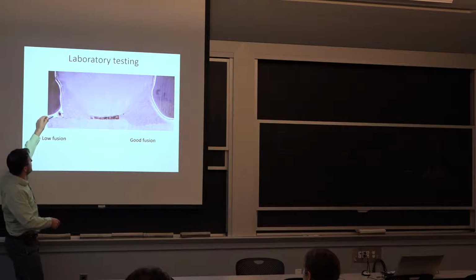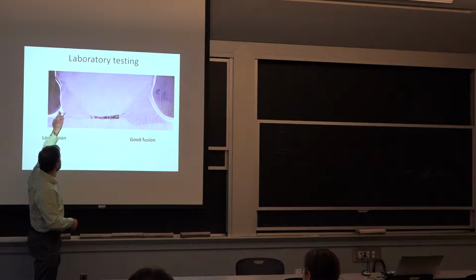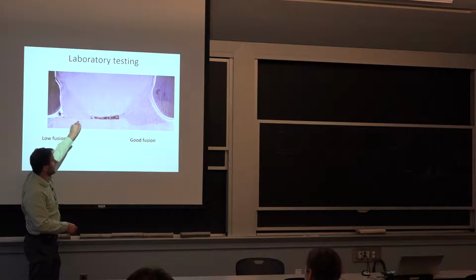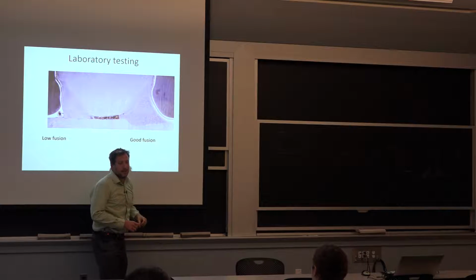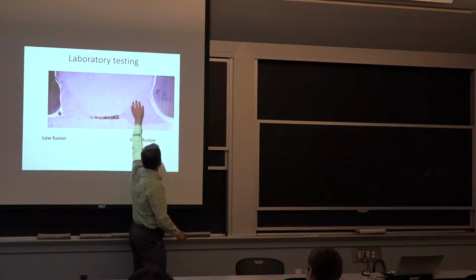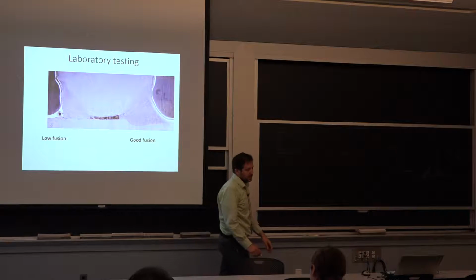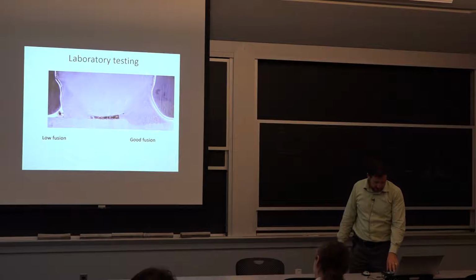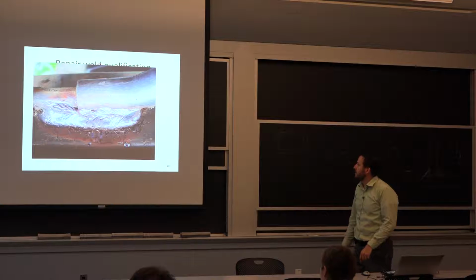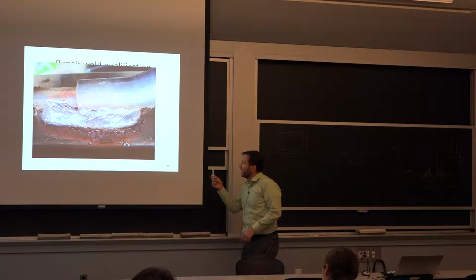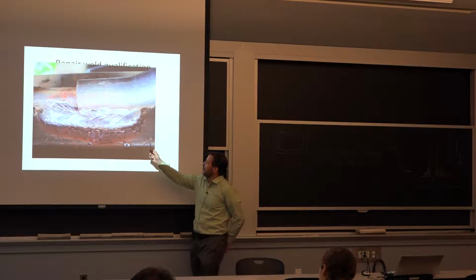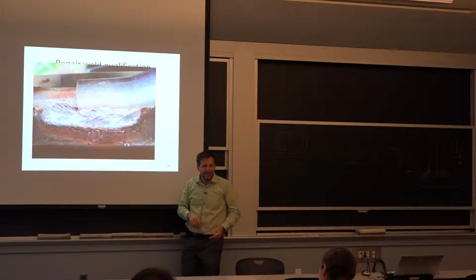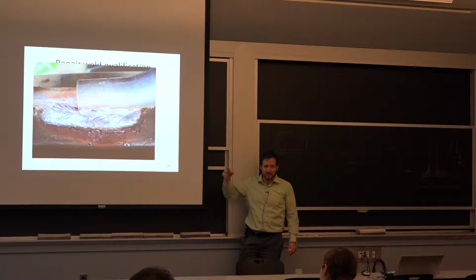So here he just went too far into putting all the heat there, and he was going to essentially have the same type of field failure. Here it was more of a compromise. So probably 2/3 of the heat or so on the side of the big bar, and then 1/3 down. Now, one thing to keep in mind, this is repair welds that we had them do so they could continue to operate. It's not all clean, right? I think the fitness equipment will show you a much smoother weld profile.